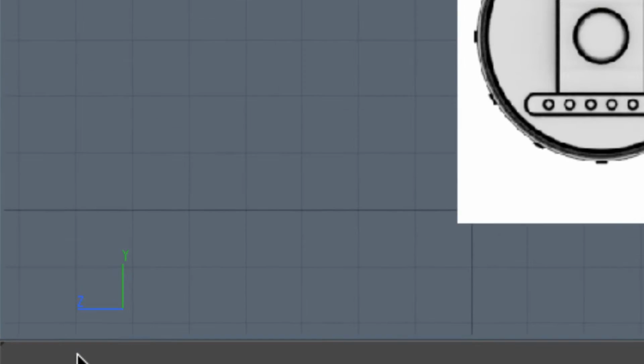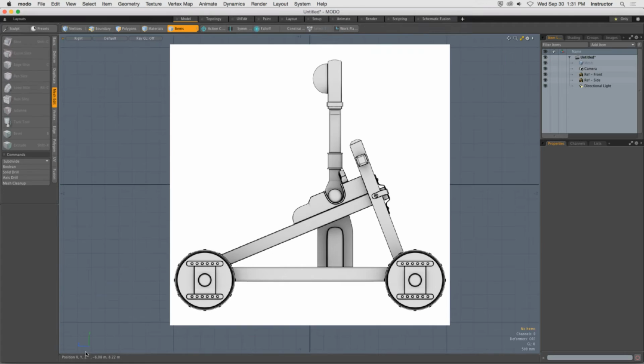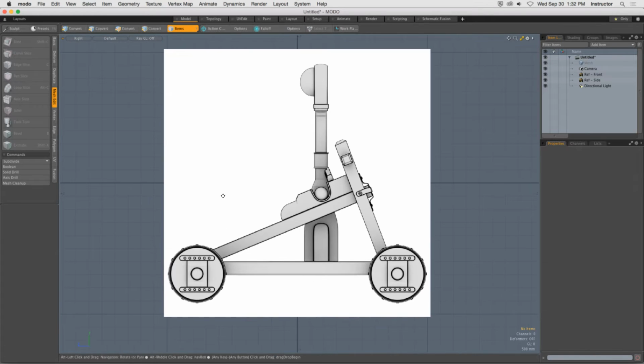The compass. And I love me the compass, right? Because this compass in every sense are like arrows in my mind. This line here points to the positive side of that axis, right? So which way is the positive z-axis? This side, screen left. Which way is up? You got it, up. In this case, it is vertical. We got lucky on that one, right? Yeah, it should be a trick question. So think of these indicator lines here as arrows. That's what I do, and it makes it easier for my little simple brain to decode exactly the orientation and the location of the positive sides of all these axes.